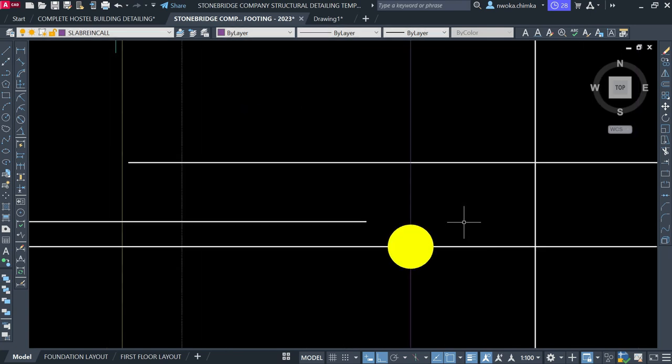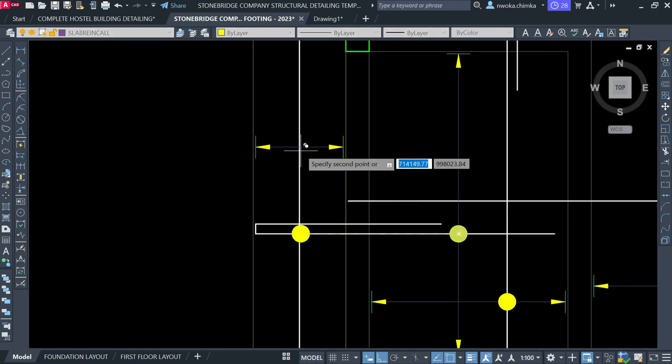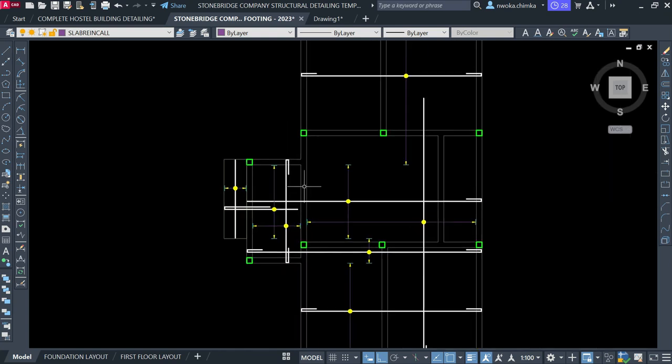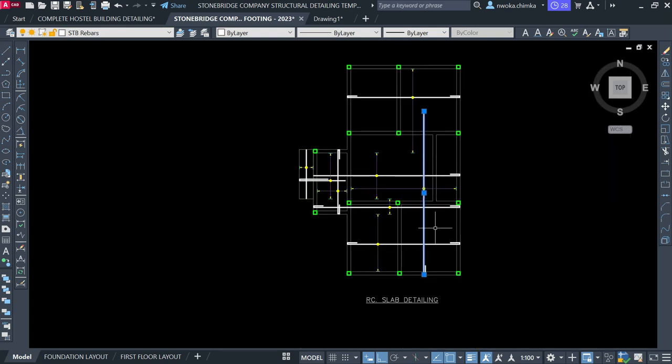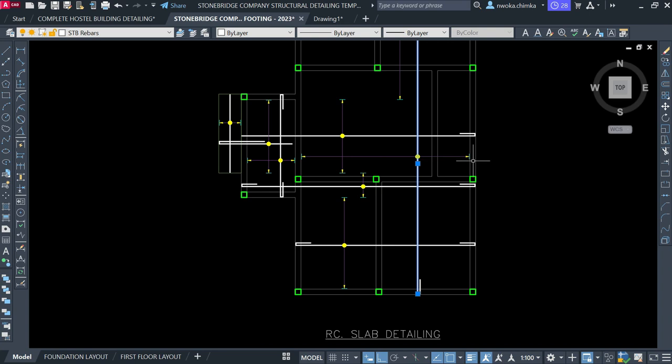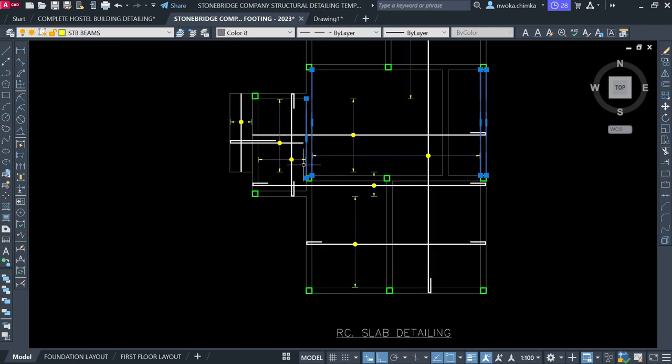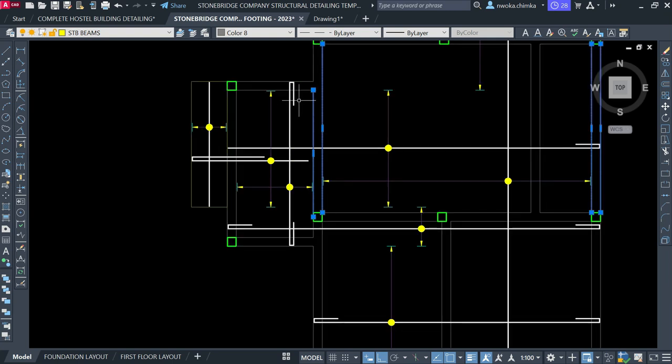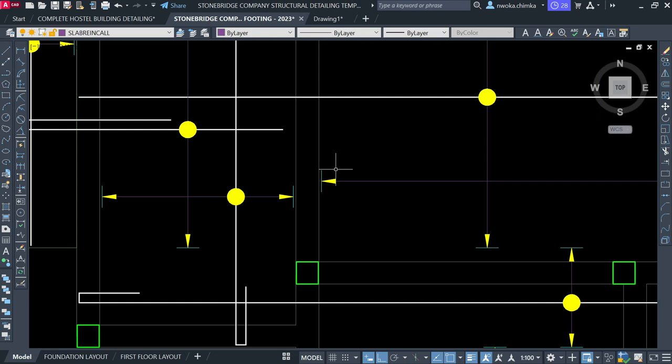Okay, now go here and copy this from here, C or CP can work, and then come here and place this here. So now, when these bars run all the way from this point of beam to this point of beam, because they have the same shape here, and then try to pass this shape, it finds that there is a different, smaller panel here. It now has to stop on this very point here.